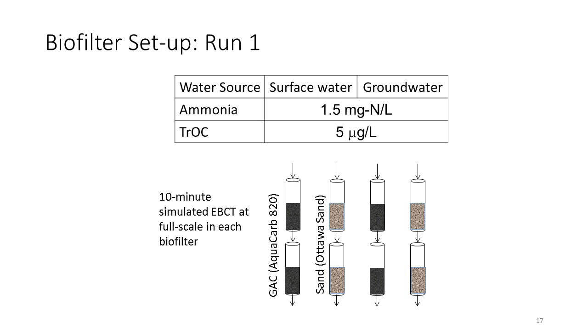So as we had mentioned before with John's presentation, our intention is to use our concentrated natural organic matter, but it took a little while to get that all figured out, and so we wanted to get a little bit of practice in the lab with our biofilters and working with nitrifiers. So we did a first run where we just used our raw waters, and we did do a settling stage just in a cold room to make sure that large particles came out, so that our turbidity was no more than about 1.5 NTUs.